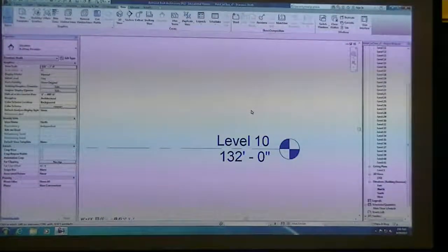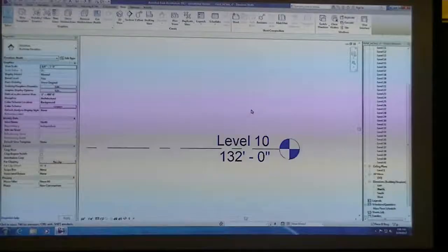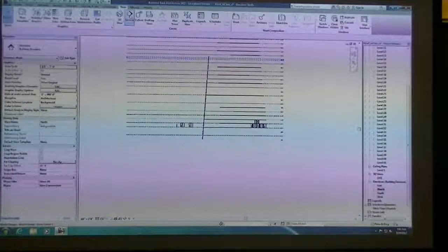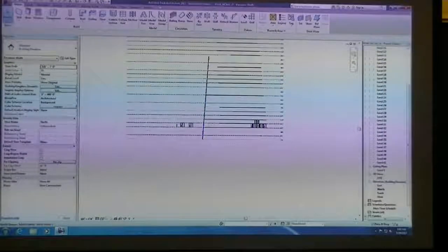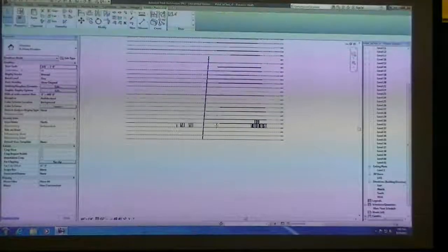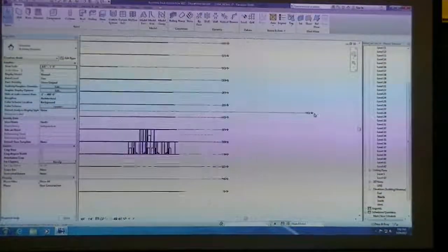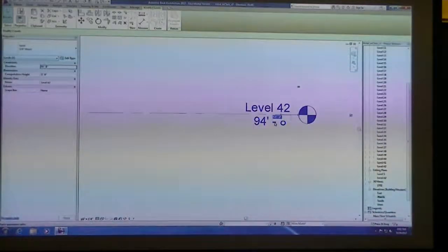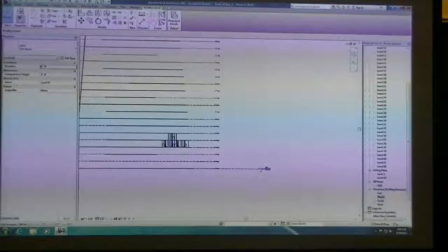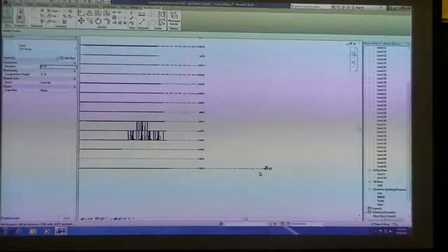So if you don't have any and you want to make a new one at the 0 plane, how do you select the 0 plane? You can go in to set up a datum. Yeah, you create just a level. Just draw a level somewhere, and then when you zoom in, just change that to 0. Because it's always going to reference where 0 is and the exact height from the Revit model, the base.